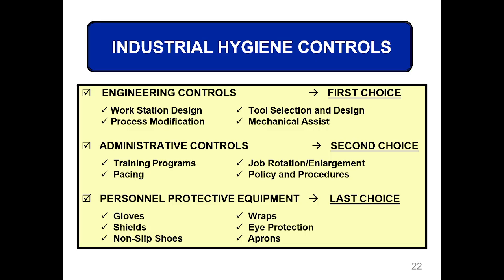So if there's a moving part and there's a machine guard, we know that no such accident related to unavailability of machine guards can happen. For example, maybe a worker has been trapped, the arm has been trapped in the moving part, or the leg has been also trapped in the moving part. Engineering controls can also be like designing an emergency switch, so that in case of an accident, someone taps it immediately. It's very close to the machine operator. Instead of you struggling to turn off the machine, just step on it. It depends on how you're going to operate the emergency switch. You can do it by stepping on it, or others there's a button.